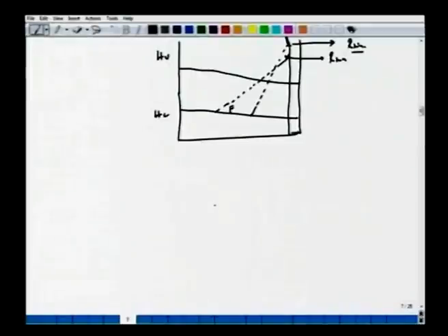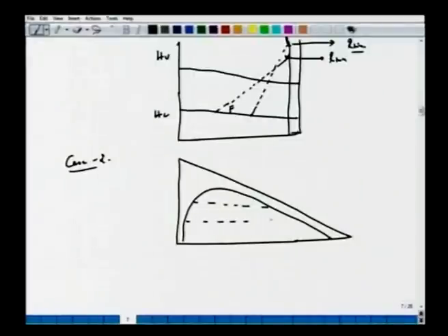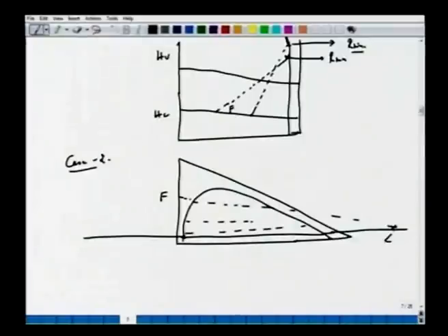So one has to do some inspection to find out the minimum amount of solvent. Similarly, if you have the tie lines, say case 2, where the tie lines are downward in the other direction, so if you have the tie lines like this, in this case also one has to extend. So if you have this R and P and Ys, if you extend like this and this, you can make out that the tie line which passes through F, if you extend, will give us del min.